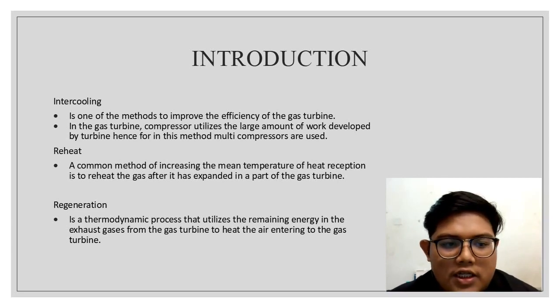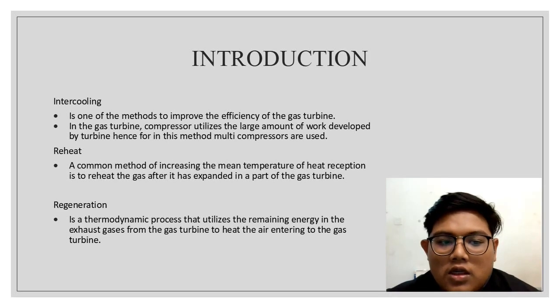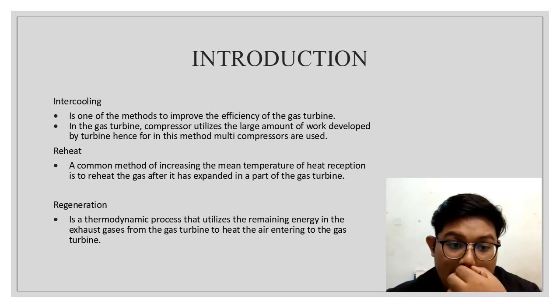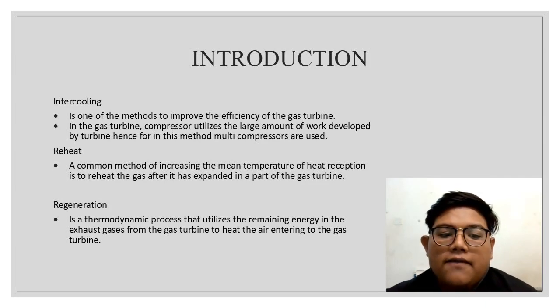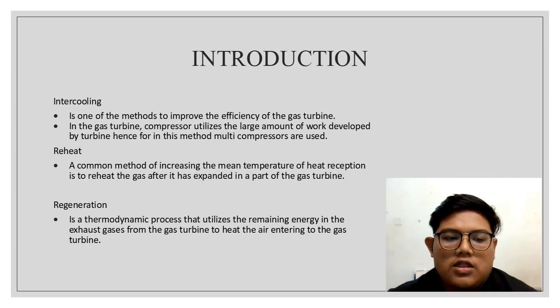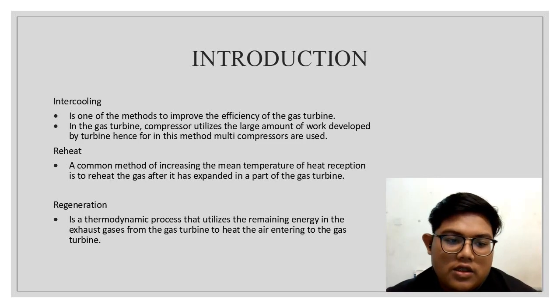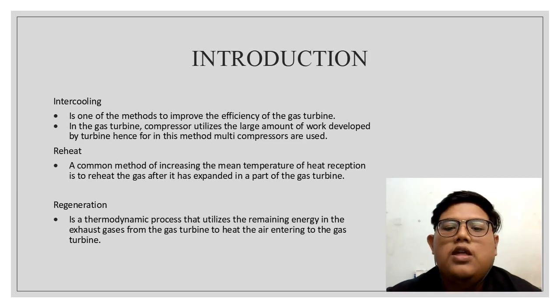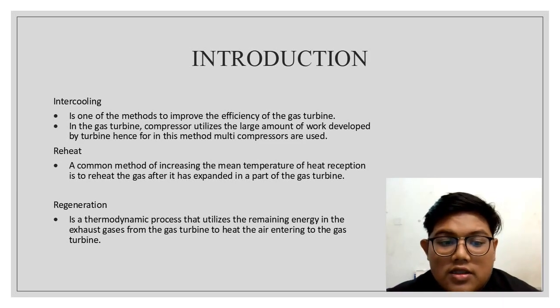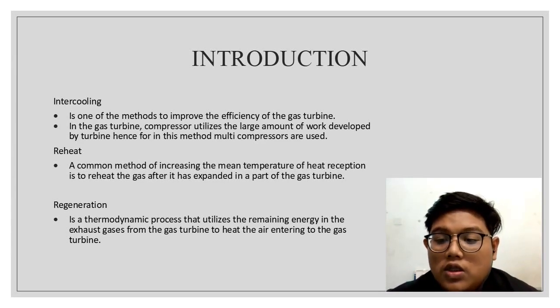Reheat is a common method of increasing the mean temperature of heat reception. It is to reheat the gas after it has expanded in a part of the gas turbine. The last one is regeneration in gas turbine cycle. Regeneration is a thermodynamic process that utilizes the remaining energy in the exhaust gases from the gas turbine to heat the air entering the gas turbine.